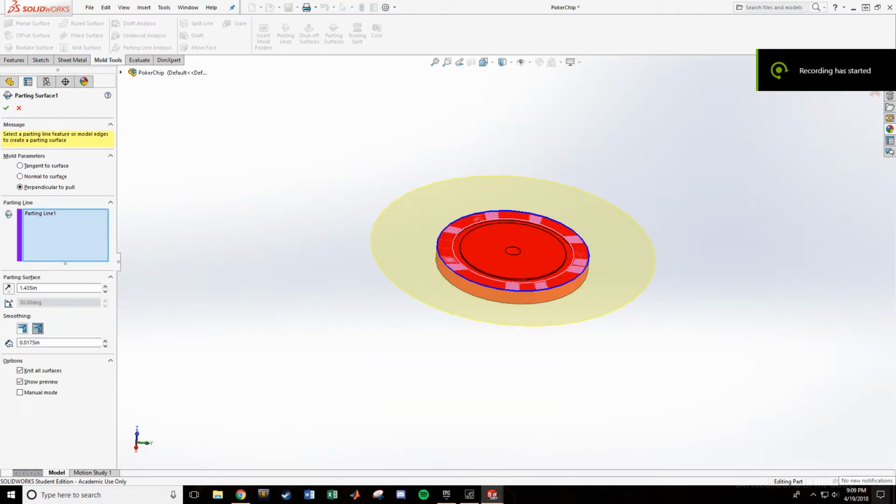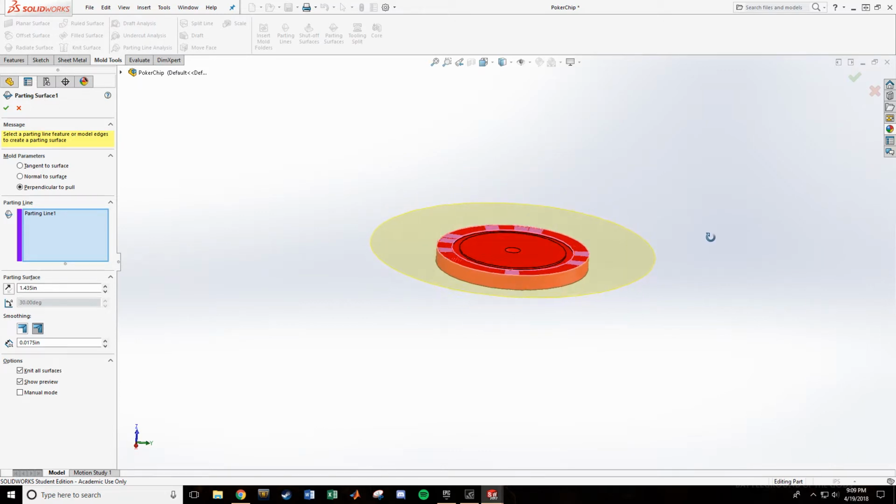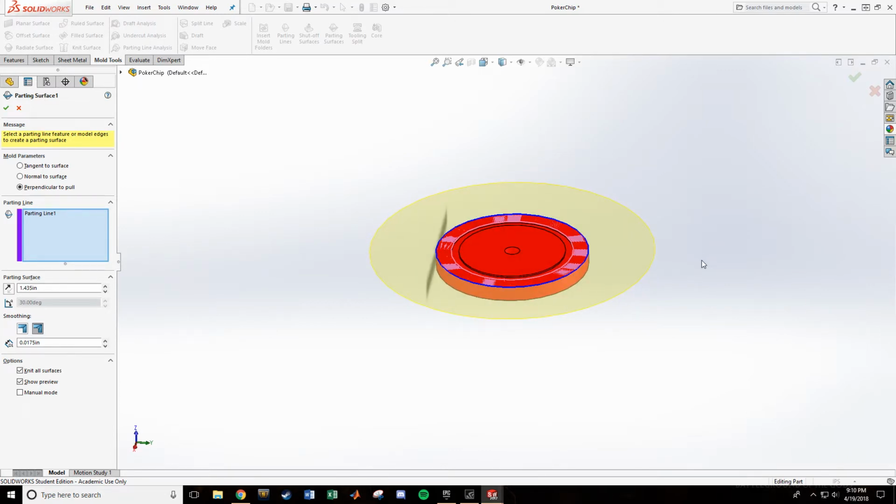Okay, so the more advanced of a part you try to mold, the more likely you're going to run into errors as you try to create the mold. The first issue that came up with SOLIDWORKS was it crashing or locking up while we were trying to make molds. So we highly recommend saving really often or after every single step when you're working through this. That way you don't lose a bunch of progress you made on your molds.